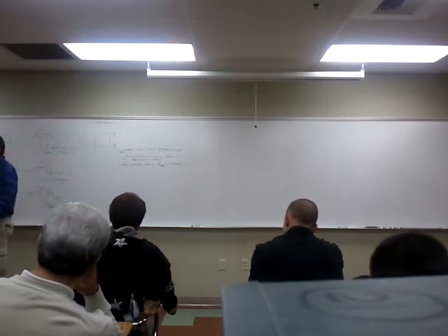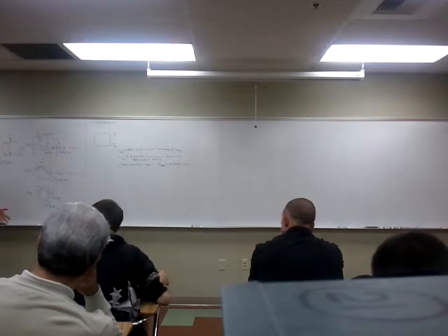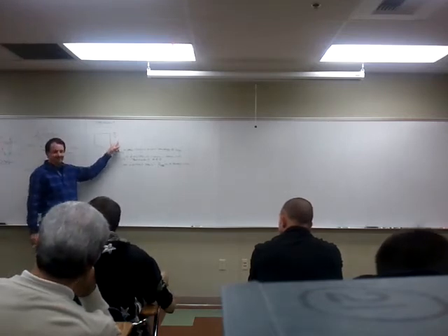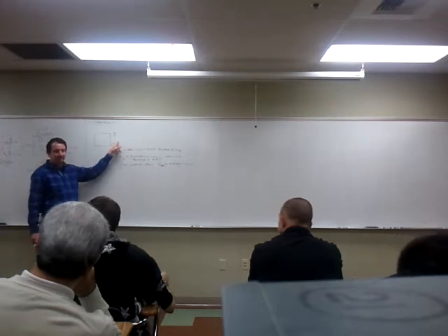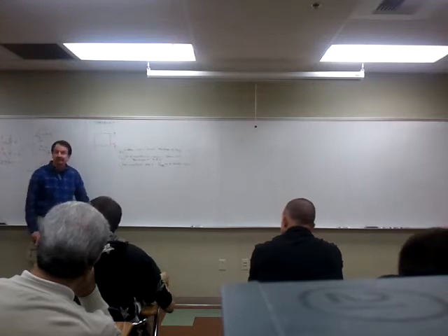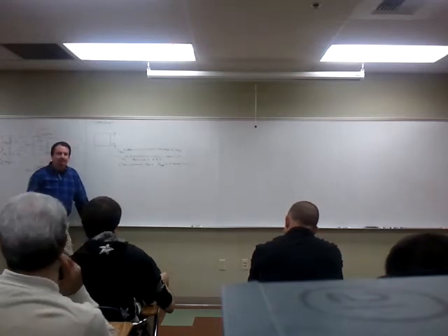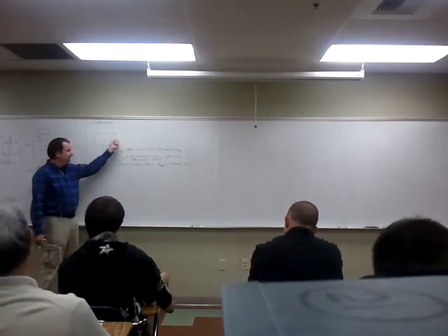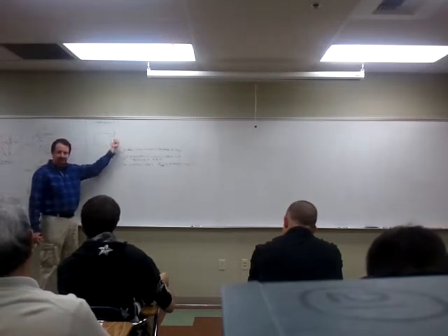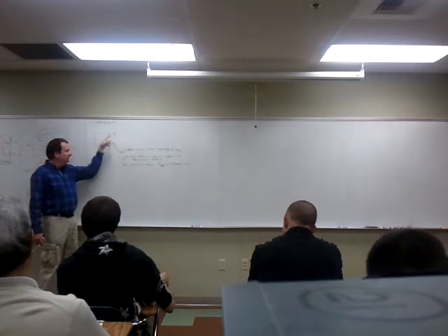I can do that mathematically, or in the real world, I can actually do it in a lab, but you can't normally short something out in lab, right? It's not a good thing. You have to know enough about the circuitry to know that shorting is not destructive. You can't measure the resistance looking back in an active circuit, but we learned if you put a rheostat on and adjust the rheostat so you get half the voltage, the only way you can get half the voltage is if the resistance of the rheostat, a variable resistor, matches the internal resistance.